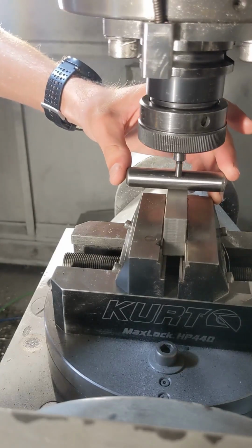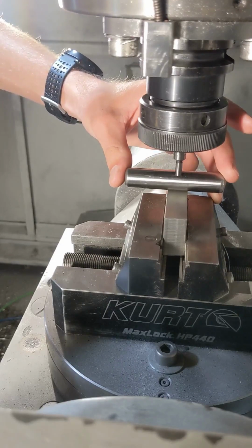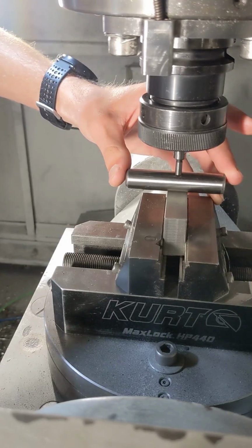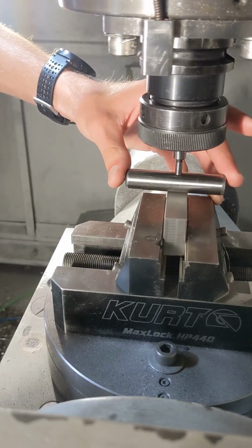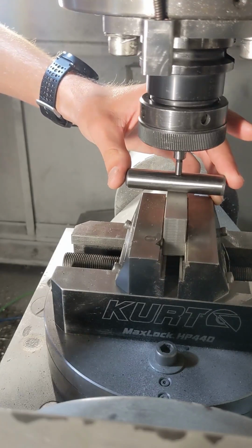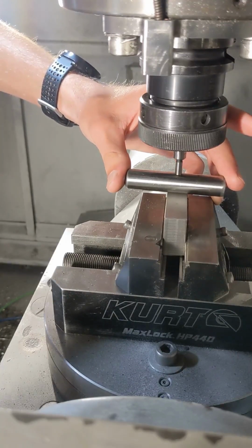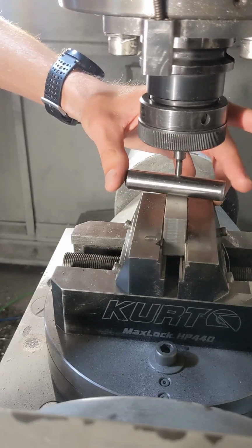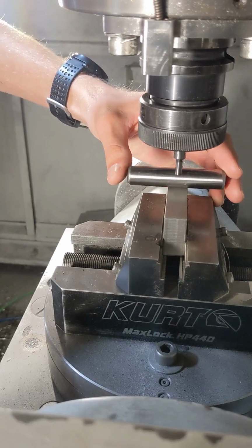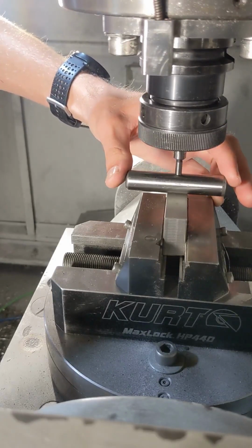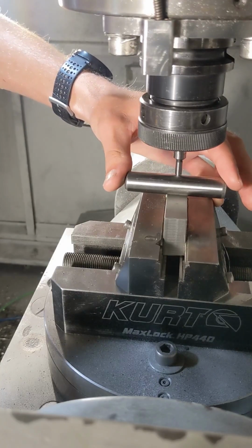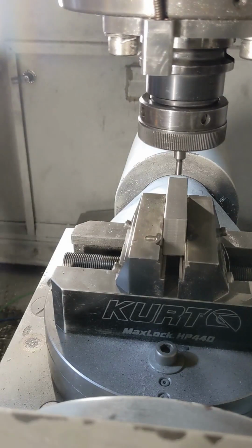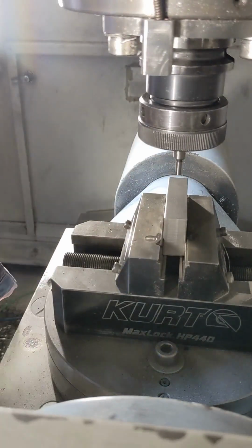So you want to try rolling the dowel pin under your tool. In our case, it's not going under, so I'm going to raise it up using the jog pendant. And then I'm going to go to the smallest increment on the jog pendant, the ×1, and just move up slowly until just when this dowel pin passes under. I'm going to go back down, just verify that it just passes under. So once you find that point, go ahead and turn the jog pendant to off, and now we will set our height in the software.